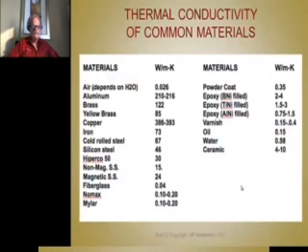It's interesting to note that the best thermal conductive materials on this list, of course, is copper, and aluminum is a close second. But look at the ones that are terrible. Air is awful, but fortunately it's a gas and you use a lot of it, so that's why it can be an effective cooling medium. Even though it's static air, it's not a good thermal conductor. It's almost, you'd call it an insulator. But then water's not that great either. We use water cooling, but it's not that great of a thermal conductor for static water either.